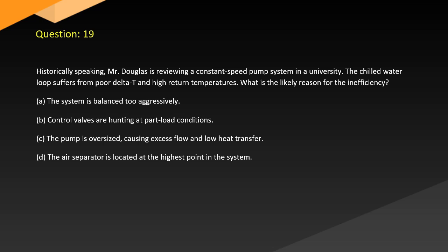A. The system is balanced too aggressively. B. Control valves are hunting at part load conditions. C. The pump is oversized, causing excess flow and low heat transfer. D. The air separator is located at the highest point in the system.